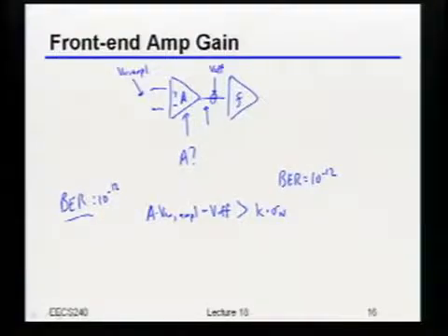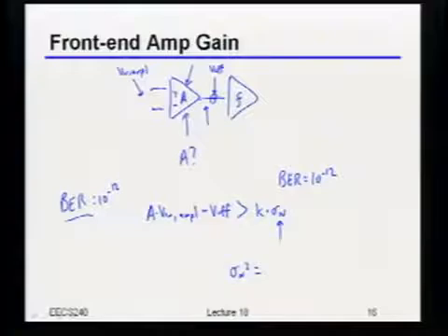So this is exactly the equation you're going to use, but is there one minor trick or detail you have to be careful about here? What do you guys think? Need to add the noise figure of the amplifier. Ah, okay. This noise actually depends on the design of the amplifier. Let's say I had a resistively loaded amplifier. What is the noise at the output of that amplifier going to be? Integrated noise, kT over C times 1 plus gamma Av, there you go.